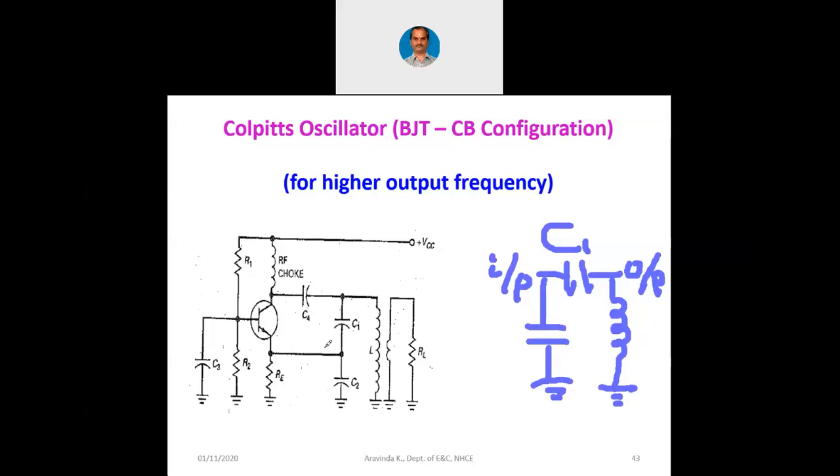Okay. Now you may think we were supposed to be having two capacitors separately and one inductor in between them. That was the normal configuration which we saw in the previous circuit. So you may think, is it not a different circuit as far as the feedback is concerned? I should say no. Why? Reason is emitter is connected to ground, AC ground is there.